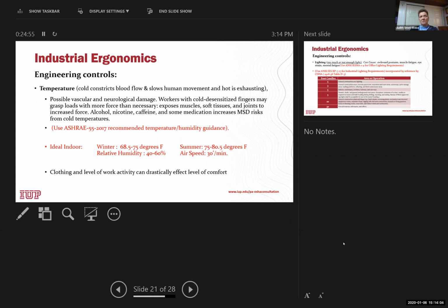So I try to use the recommendation from ASHRAE 55/2017. It recommends temperature and humidity. For example, the ideal indoor temperature in the wintertime should be 68.5 to 75 degrees Fahrenheit with a relative humidity of 40 to 60%. In the summer, you can use the range from 75 to 80.5 degrees Fahrenheit, relative humidity 40 to 60%, and an airspeed of 30 feet per minute as a guideline.